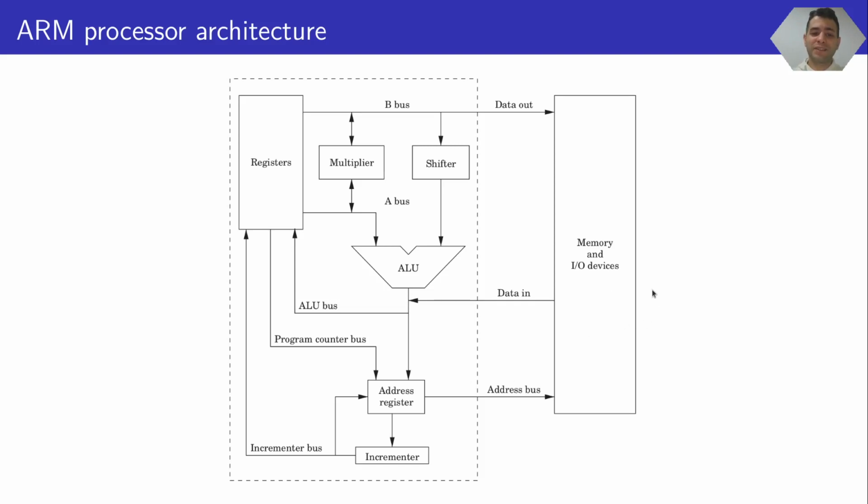The base address can be incremented, and the incremented value can be stored back to the registers. This allows the processor to increment the program counter after each instruction and to implement a certain type of addressing mode where a pointer is automatically incremented after each memory access.